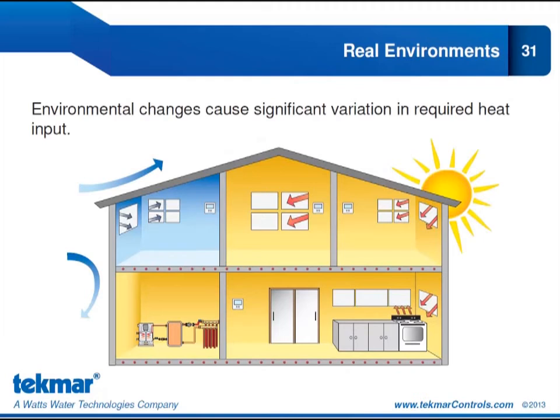We can see from the image we have here, perhaps there's one room that, because of where it's located, is typically a lot cooler than the other rooms. And perhaps we have a room over here that experiences a lot of solar gain, so it is much warmer than the other rooms. These are all factors that we have to take into consideration to optimize our system and not treat every single zone as if it were the same.